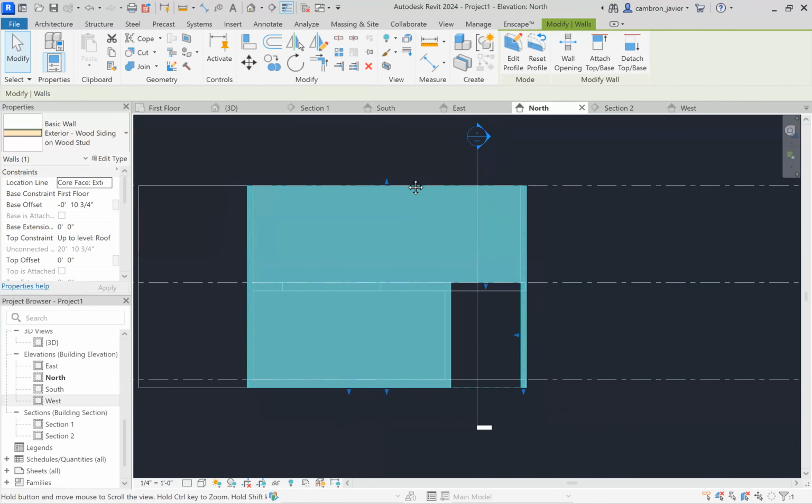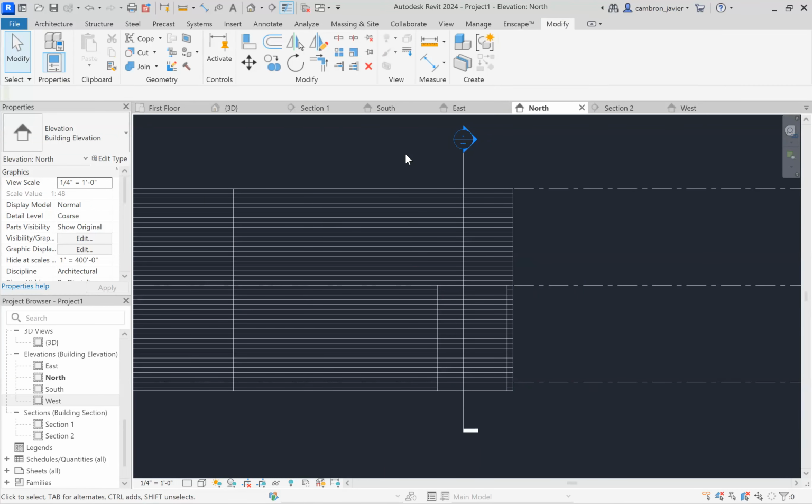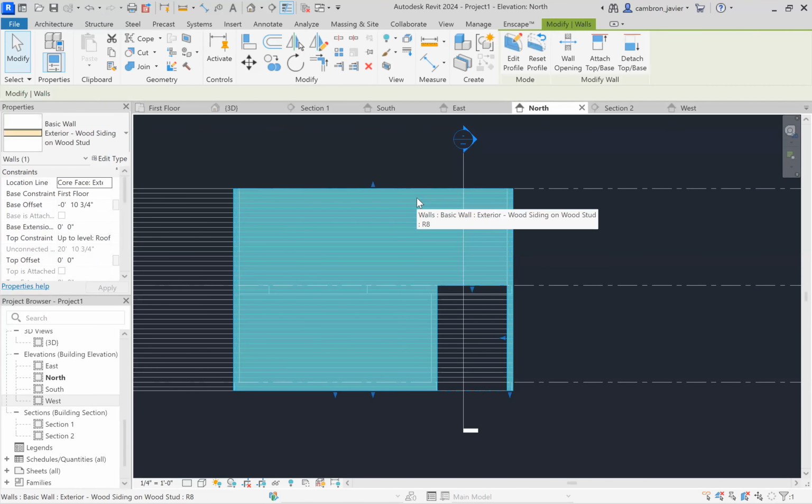I think what maybe happened has to do with an issue when we created the floor, right? We got those two error signs or those two kind of questions at the very beginning, when we hit to create the floor, and they talked about adding the walls from below to join the floors, and then do you want the floors to be joined together with the wall components, right? And we hit yes and yes, which is what we should do. But occasionally what ends up happening is that Revit has to do a lot of thinking.